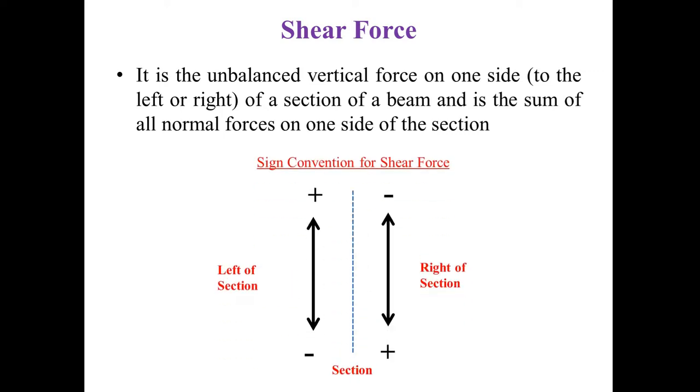So let us talk about the sign convention for the shear force. When you are going for problem solving, we have to take the sign convention for the shear force. For that, we normally take the section over here. Left hand side of the section, upward force positive, downward force negative. Similarly, right hand side of the section, upward force negative, downward force positive. So that is the shear force. Basically, shear action means a cutting action.